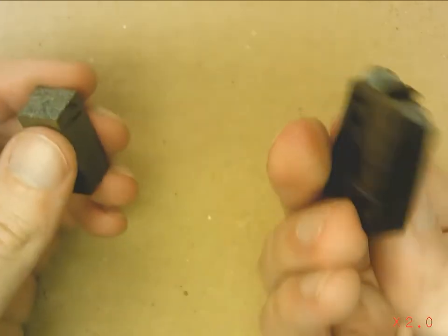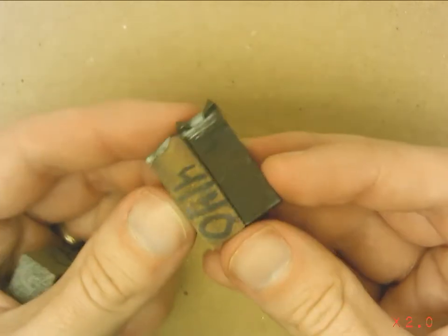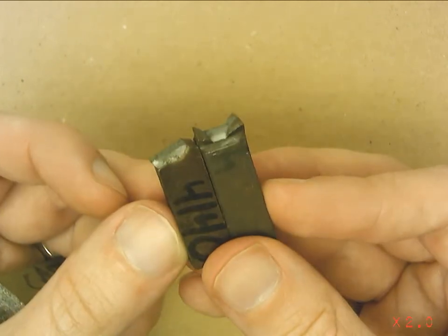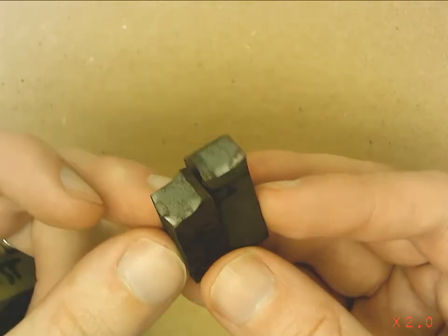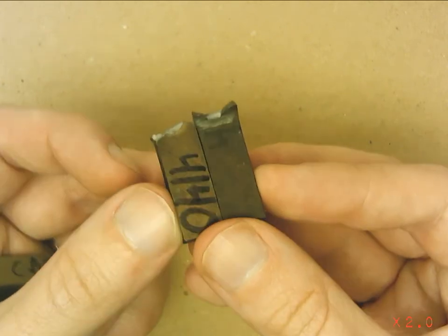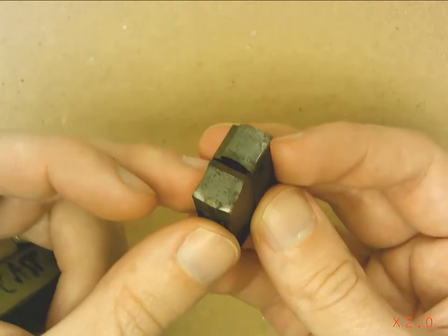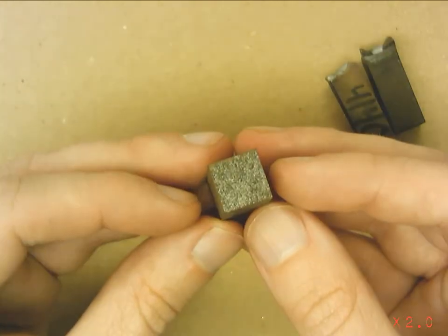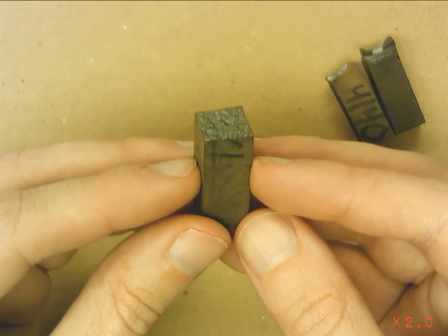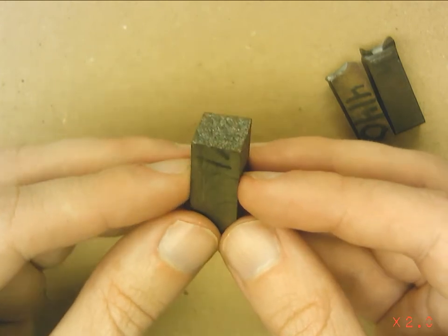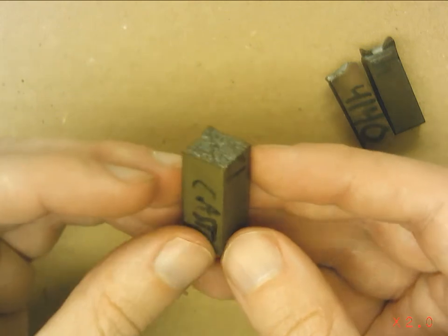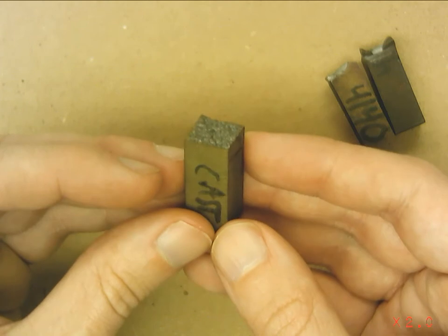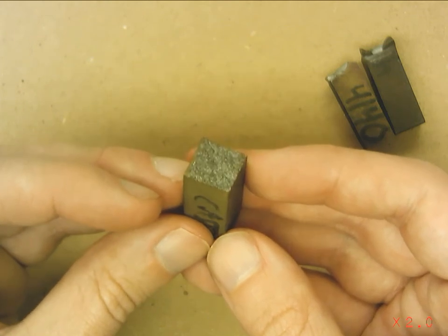So this one was a 4140. There we go. So that's a chromium molybdenum alloy steel, medium carbon. It's very weldable, pretty common on, say, the Baja car, automotive parts, stuff like that. Of course, this is cast iron, used for machine bases, engine blocks, brake discs, of course, cookware, but that's not a big part of the industry. But it is characteristically very brittle and has terrible impact toughness.